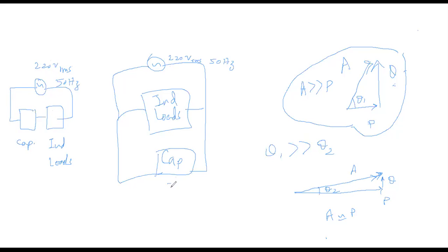So a power factor correction device such as a capacitor is always attached in parallel to the load. And why do we use a capacitor? Because I told you that the capacitor behaves oppositely to an inductor. In an inductor, the current lags the voltage. I had told you a very convenient term, it is called CIVIL. In a capacitor, I leads V, and in an inductor, I lags V. That means V leads I.